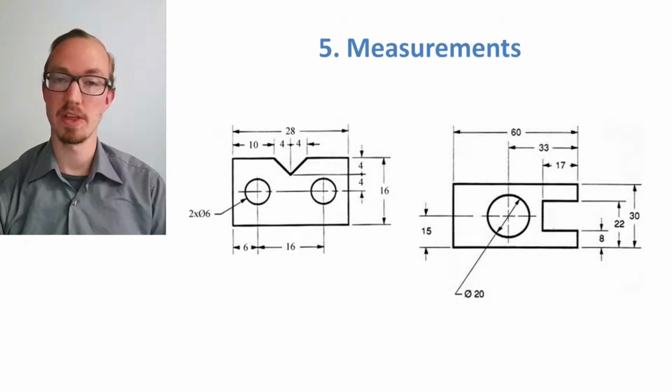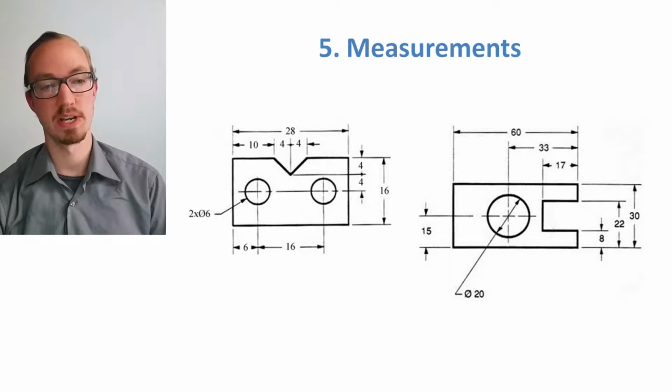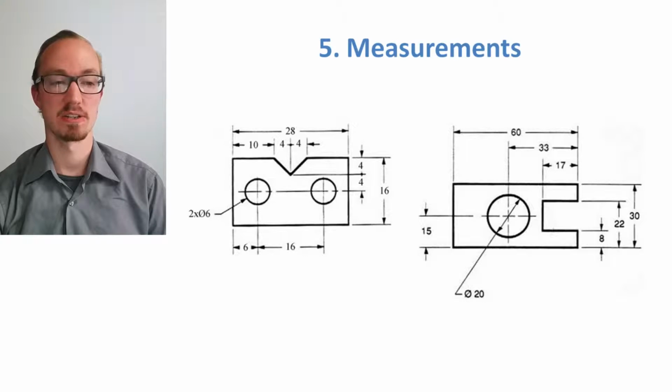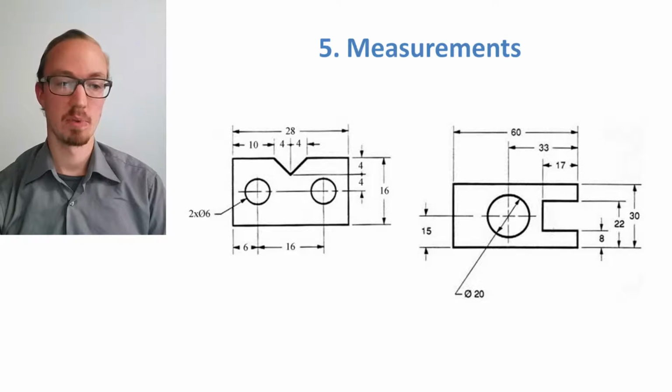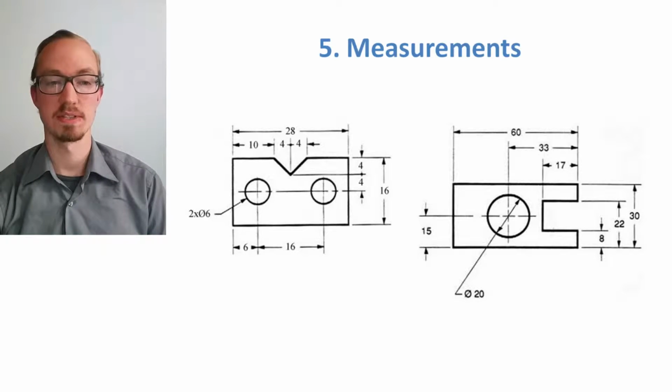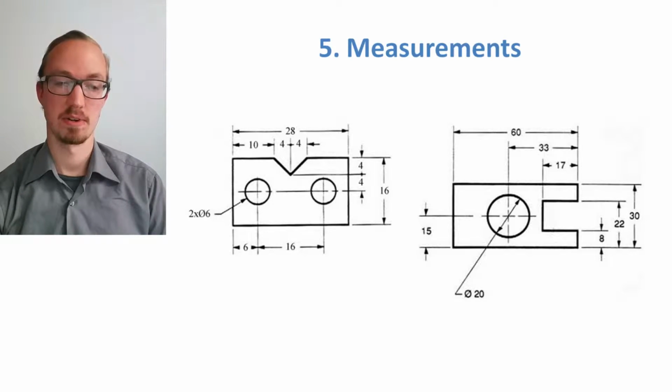After doing this, you add the measurements. Here are also different techniques. For example, on the left we have measurements that are stacked on themselves, so you also have to stack the tolerances. Whereas on the right, all tolerances, all measurements are related to just one point on the product, from which it's then measured.